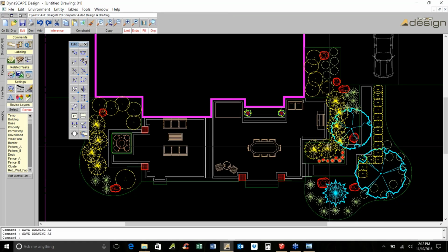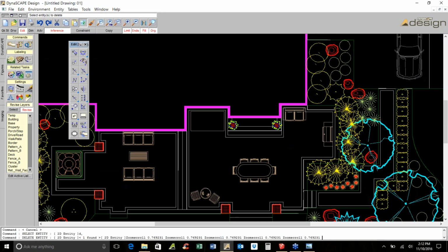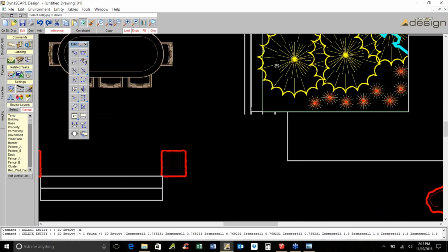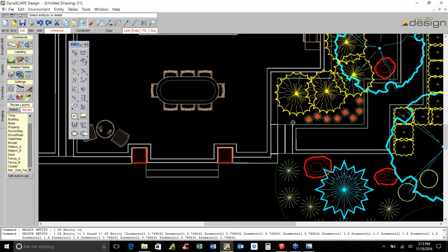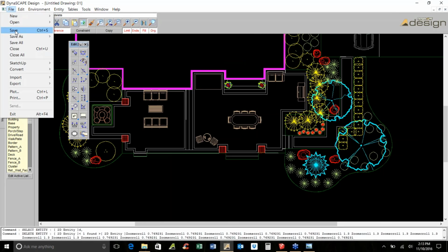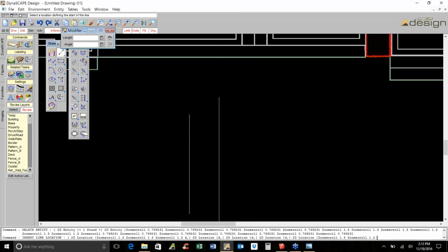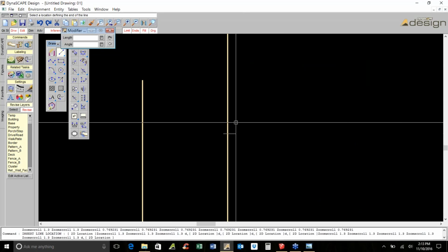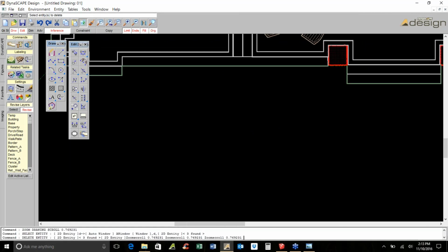Very fast. Yeah. The one thing I want to tell everybody is that this is a really good gauge on how well you're drafting, and you'll see in a minute. You want all your lines to be intersecting nicely, because it's going to create these spaces that, if they're not joined, mean you have to do a lot of cleanup work. So draft cleanly, have lines intersecting. Don't be lazy with something like a sidewalk like this and then something else; that's going to create just a ton of nightmares in SketchUp. So let's just get rid of that.